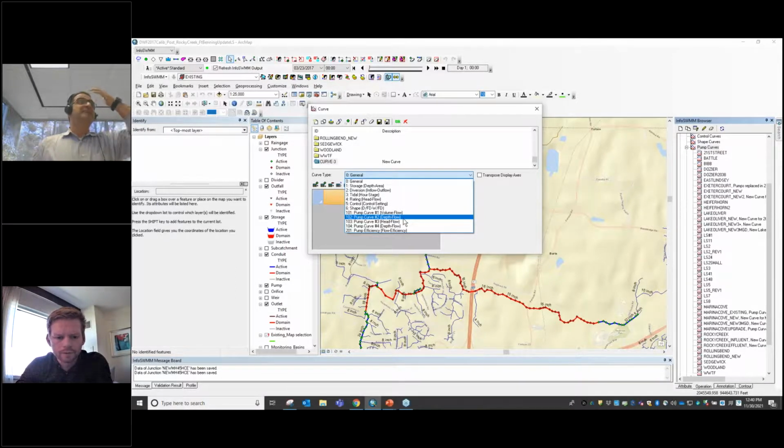So one of them, unless Bob has something else, the depth can be, you know, if the depth in the wet well is 3 feet above invert, this is the flow that's coming out, versus those 3 feet might be only 1 foot above the pump invert. Or actually the head is really the total head the pump is seeing.